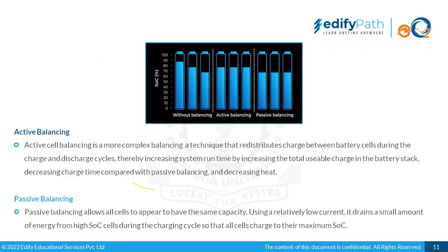So here we are seeing conditions, say SOC percentage. In the first case, it is showing imbalancing of the cells. Three cells are at different voltage at a certain point of time. It should not be there. At any instant, they should be at equal voltage if it is a balanced battery.